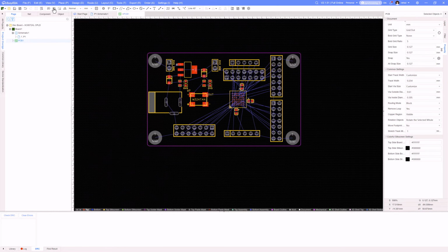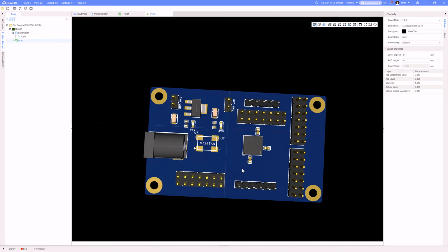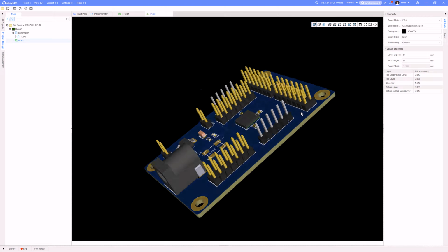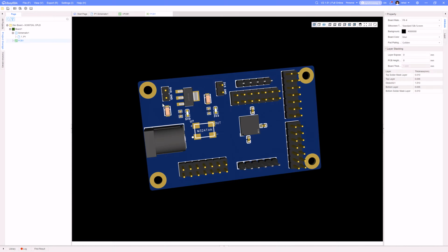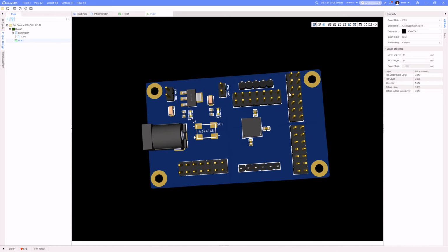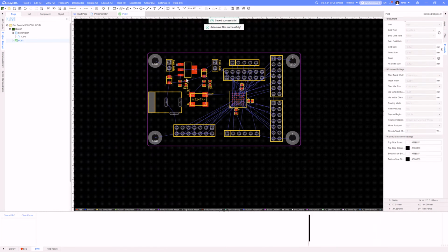Okay. Let's see what that looks like. Okay, so there I've got something that looks like that, and yeah, not too bad. Maybe I want to pull this down a little bit, but that should be pretty close. I can bring in power either here or here. I also have a 3 volt rail I can touch here with the meter or scope. I have an oscillator that I can provide into this CPLD, and then I have 4 output ports that are 8 I/O pins each. Okay, so that's all looking decent.